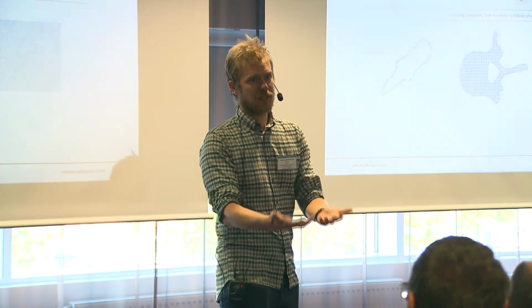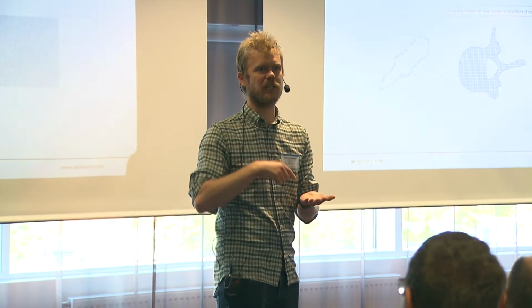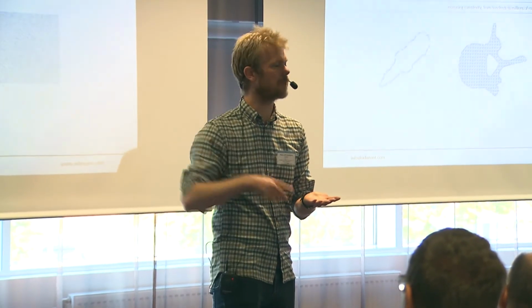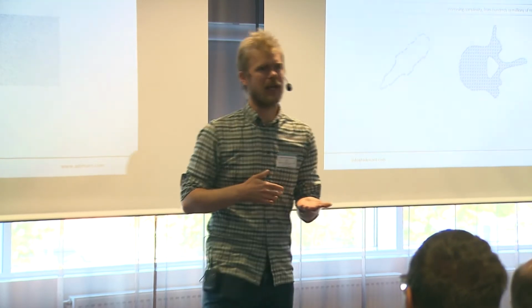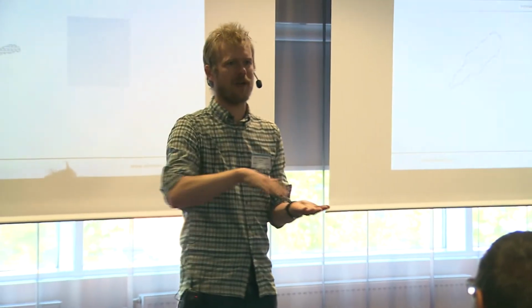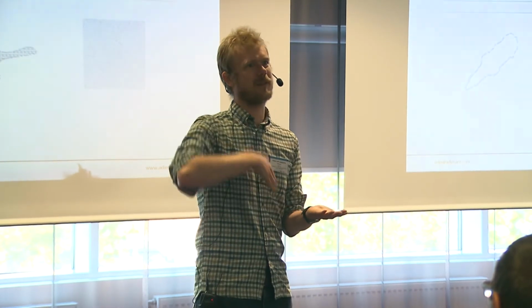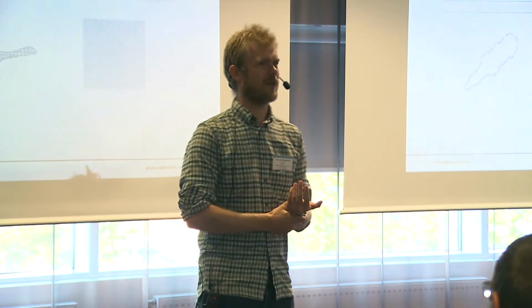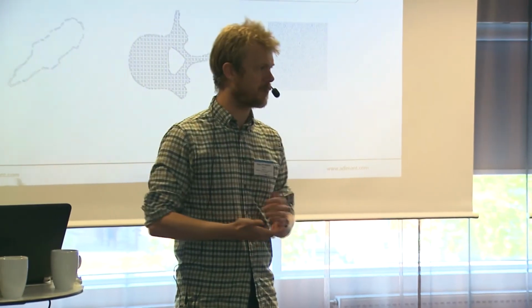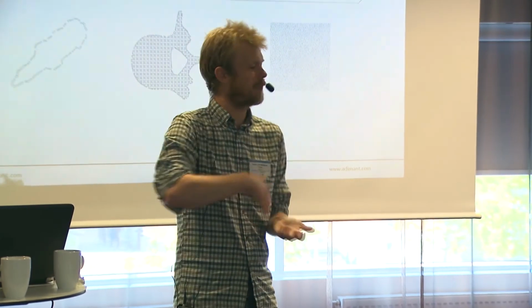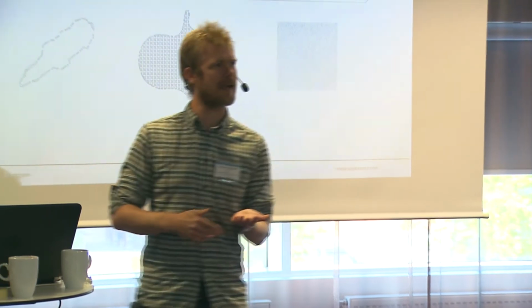So for example, some machines would load in 1 layer at a time, look at all the contours, and then start to calculate the hatches, so the actual laser motion. And this can be time consuming when you have thousands and thousands of polygons. So I had a case where they could shoot the layer in 5 minutes, as in Olaf's case, but it took 25 minutes for the machine to calculate the paths for the next layer. So that meant that what was meant to be a 20-day build job turned out to be a 3-month build job, because that's just how the software works. It calculates these tracks online because you don't want to waste hard disk space.